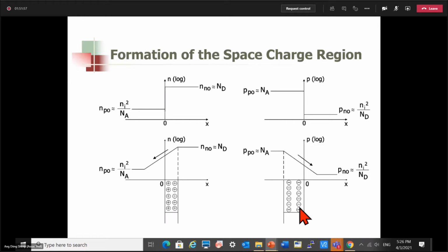There is no reason why the width of the space charge region on the P side should always be bigger than that on the N side. In this drawing, I have implicitly assumed that the N side doping is higher than the P side doping. I will come to this point shortly. This is actually referring to space charge neutrality. Okay. Thank you, Prof.